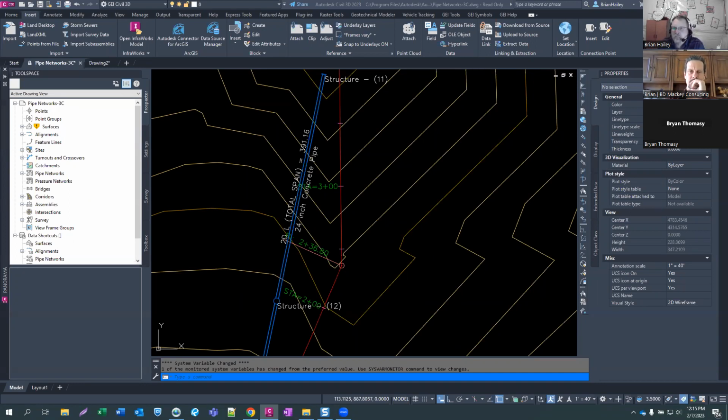And the way I like to do it is based off of, so back in the day when Civil 3D first came out, Autodesk was like 1 object per drawing. So your alignment goes in 1 drawing. If you have 50 alignments in this project, they all go in separate drawings. I found that just to be ridiculous. So I like to take my roadway design and I'll put those alignments and those profiles into a drawing to create my corridor. And then I will data reference those out as needed. So my plan production drawing, I will data reference in the necessary alignments and profiles and leave all the other junk behind.